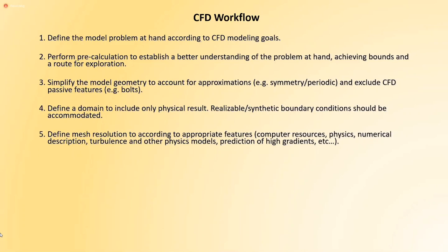I mean, if there's a bolt inserted inside a hole, you don't care about the results there. There's no need to model it. You're just going to get a higher aspect ratio between the full domain and the smallest part of your feature.